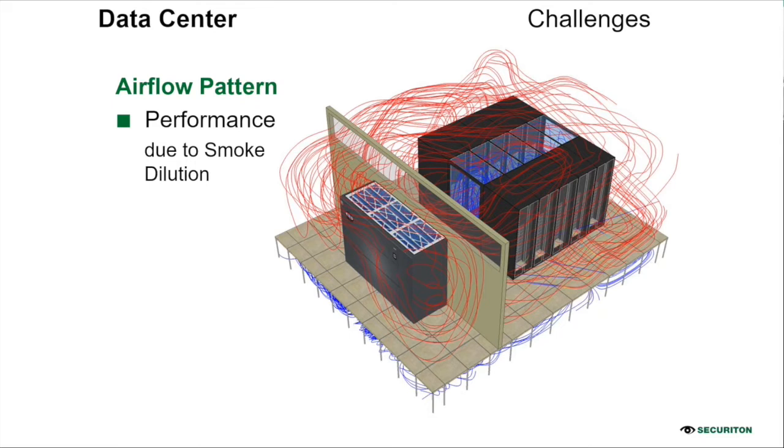There are CRAC units working to cool the space, in addition to many fans on servers and air pushing up out of raised floors, all creating airflow patterns unique to data centers. The increased air velocity and airflow pose a challenge to fire detection because they make it harder for enough fire byproducts to reach a smoke sensor quickly.